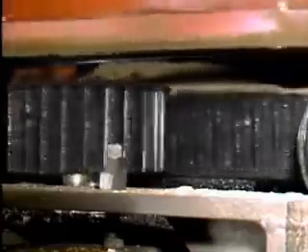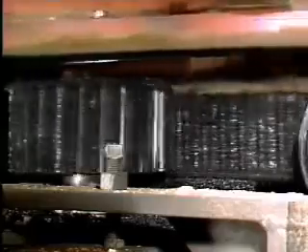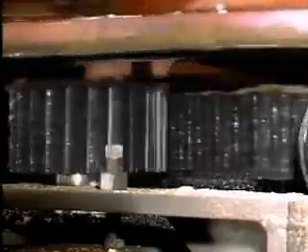Grease is usually the best choice in situations where a lubricant must stay in place. For example, grease's ability to stay in place makes it the best lubricant for exposed gears. There's no gearbox to hold a supply of lubricant, so the lubricant used must be able to stick to the teeth.